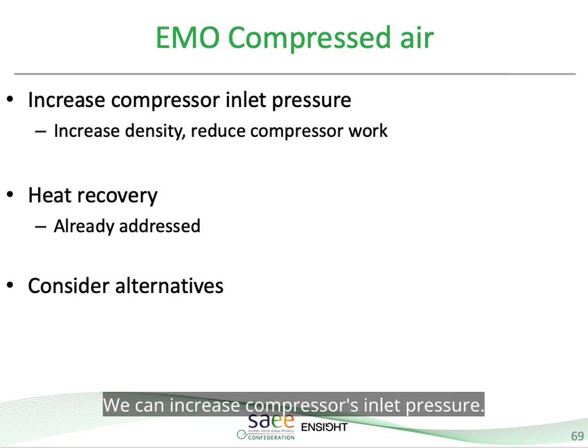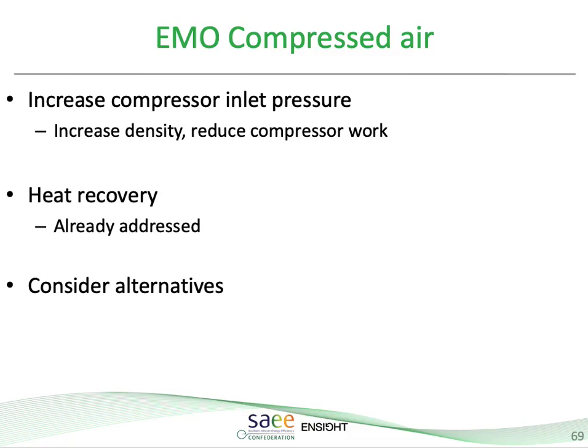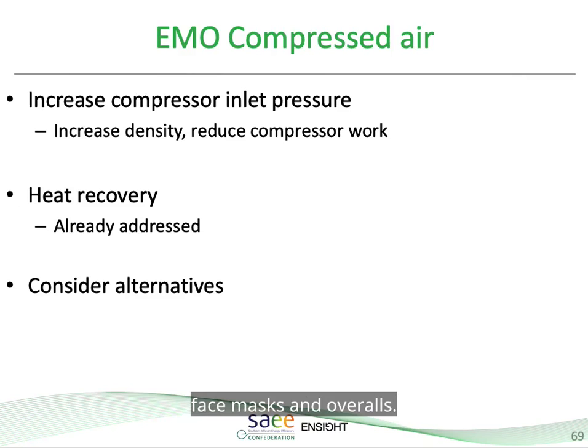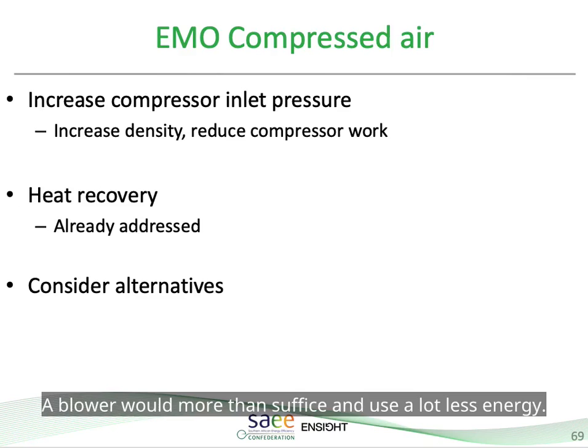We can increase the compressor's inlet pressure. We can determine if heat recovery is possible, and we can consider alternatives. For example, a compressor is not needed to clean off face masks and overalls. A blower would more than suffice and use a lot less energy.